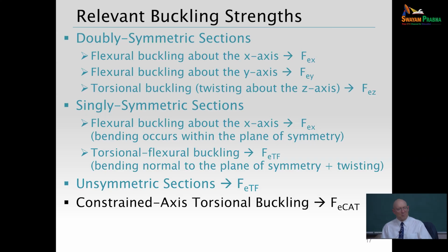And this mode of buckling often happens when we have, say for instance, metal buildings or any buildings where maybe you have possibly a window wall and you have columns that are supporting the structure of that window wall, and you can brace one flange of the column there within the plane of the wall, but you don't have bracing to the other flange that's offset from the wall. So in that case, well, you're preventing lateral displacement at the axis where you're attaching to bracing within the wall.